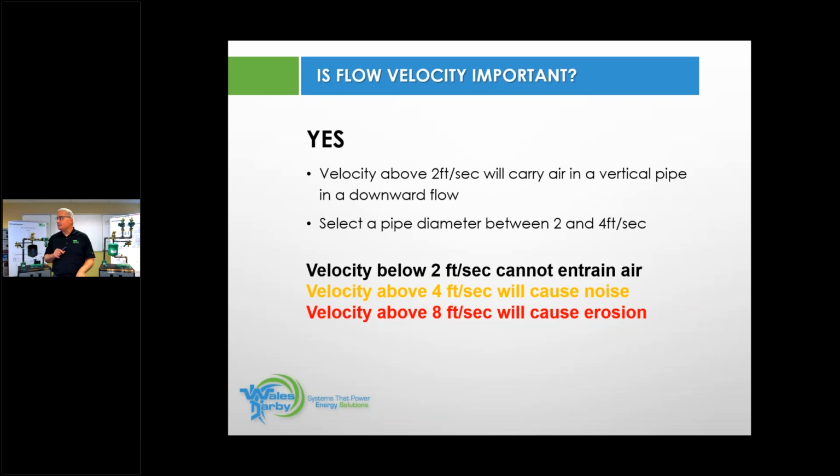We got a question. A gentleman asked, you referenced PEX piping. He asked about crimp style and expansion style. Are there differences? Yes, there is. We're the Uponor rep, so I'm going to be referring to Uponor with the expansion side. And all of our literature will say that we've got a 30% greater flow rate with our fitting on the expansion style versus crimp.